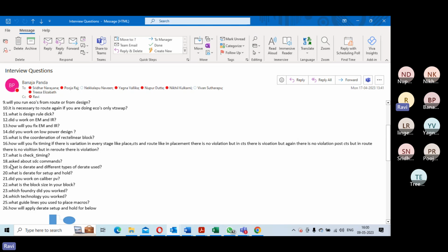But more or less the difference will be very minimal for that path, so you will not over-add pessimism by creating a completely different derate, even though theoretically there could be a small variation due to IR drop difference between the launch cycle and the capture cycle.